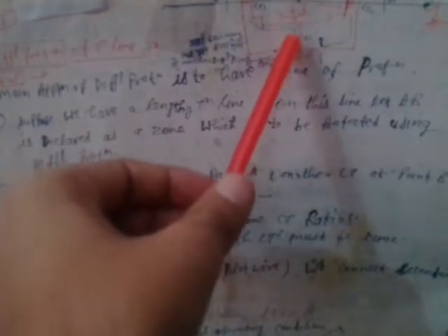And that is expected, that the relay should not operate for any fault which is external to this protected zone AB. The relay should only operate when there is a fault within this protected zone AB, and then and only then the relay should operate. So we have seen two cases. Case number one is the normal operating condition. The difference of current in the relay operating coil is 0, so the relay will not operate.